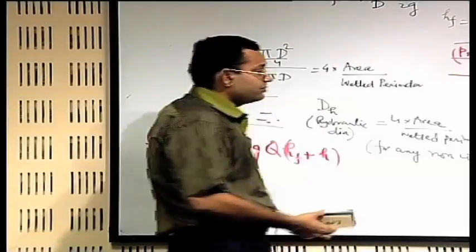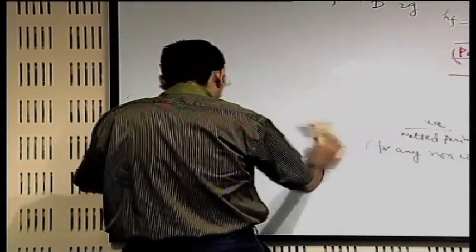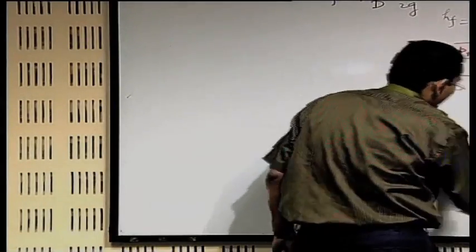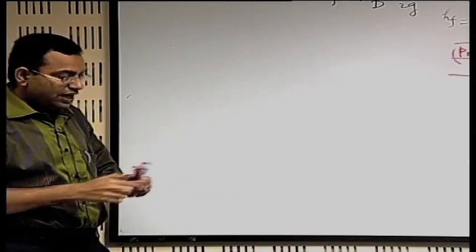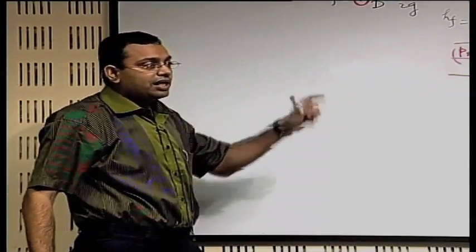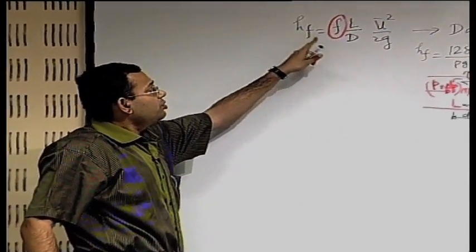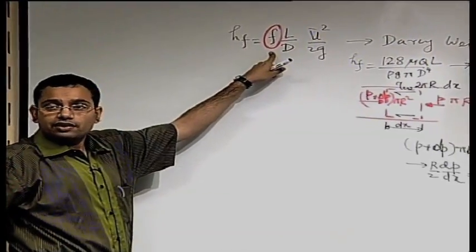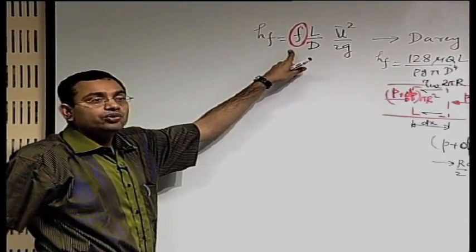So now, as engineers, one of the important things that we have to understand is the friction factor, because if you see this Darcy-Weisbach equation, you can estimate the head loss completely if you know the friction factor. So the friction factor, how do you know?